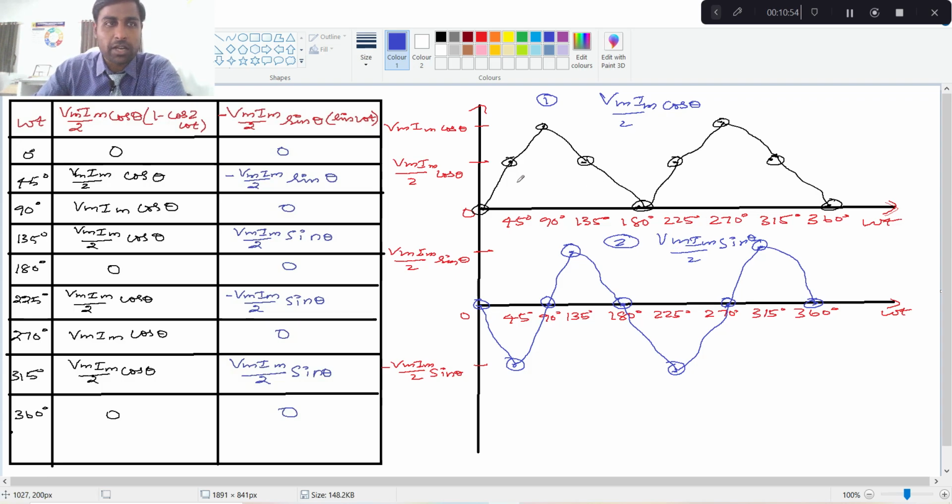And you see this expression now, you can see that there are no negative terms. All values become positive here. Maybe this graph comes to 0, but it never gets to negative. So this is actually the power curve. This is the power curve for the first expression. This is the second expression in the power expression. Now you see this expression never becomes 0. And what it actually means, if my power is not getting to 0, is that all the power is transferred from source to load. So all this power will be real power because it is flowing from source to load.